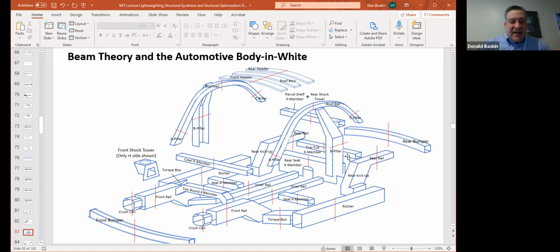I can kind of speculate how this must have unfolded at BMW. It must have been like, well, this car weighs 5,000 pounds. If we're going to get, say, somewhere between 15,000 and 25,000 pounds capability when it's turned over, we're going to need a lot of heavy steel up there to support all that weight. So, okay, let's start putting high strength martensitic steel up there. Well, gee, you need a really thick wall thickness. Now we've got a problem because our CG's crept up. What do we do? Okay, how about carbon fiber?